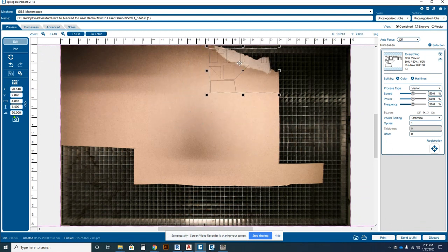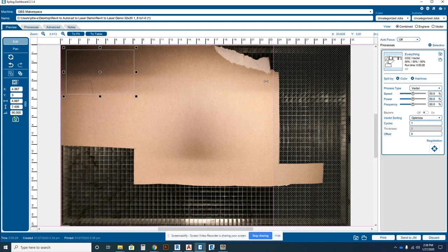I also want to avoid any rip. You'll see that this laser cutter is kind of cool because it has a camera. And so it's actually looking at the exact piece of paper. In this case, it's 1/8 inch thick chipboard, which is like a cardboard, that's on the machine. This bed size is 20 inches by 32. But you also see that you can drag out areas to make sure that you don't cut in certain regions. So if I did this, any material or any line work that was over in this dotted area would not actually laser cut.